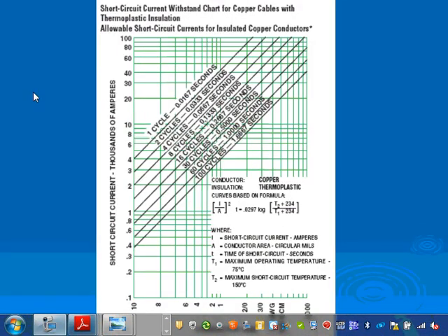And I feel sorry for the low voltage guys and gals, because this is really above people's heads sometimes. How many of you guys size conductors? How many of you guys have sized a conductor taking into consideration the short circuit? I guarantee you, unless you did medium voltage, you never thought of short circuit when you size a conductor, right? Now, this becomes very, very important, guys, when it comes to high voltage.